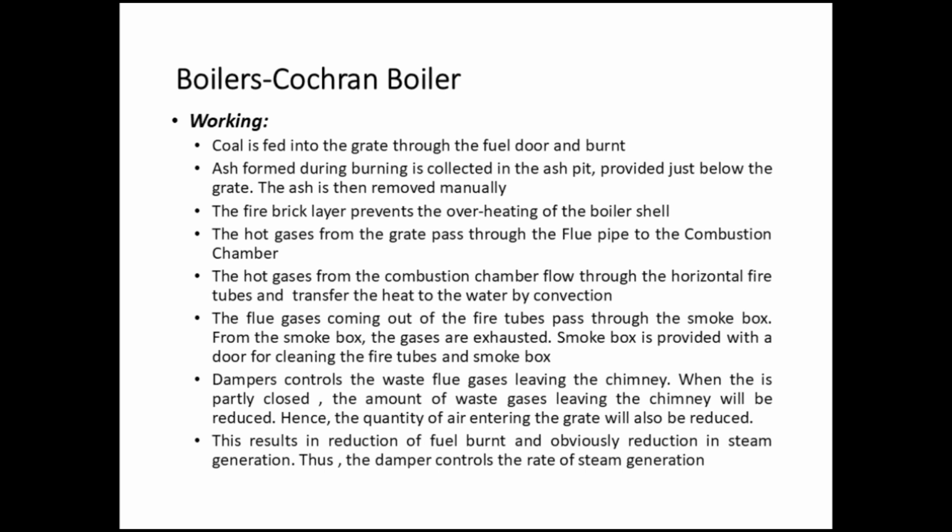Dampers control the waste flue gases leaving the chimney. When it is partly closed, the amount of waste gases leaving the chimney will be reduced. Hence, the quantity of air entering the grate will also be reduced. This results in reduction of fuel burnt and obviously reduction in steam generation. Thus, the damper controls the rate of steam generation.